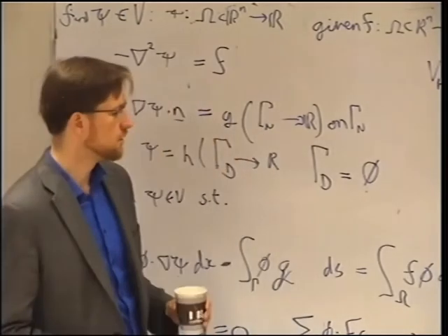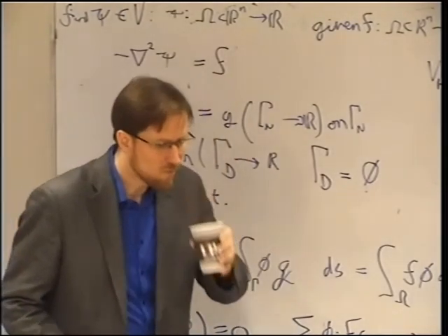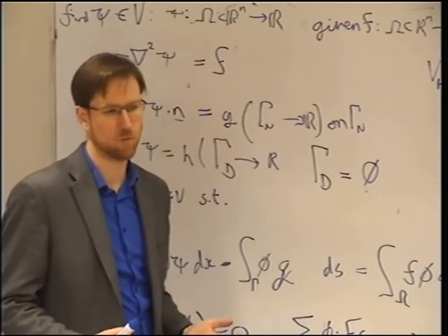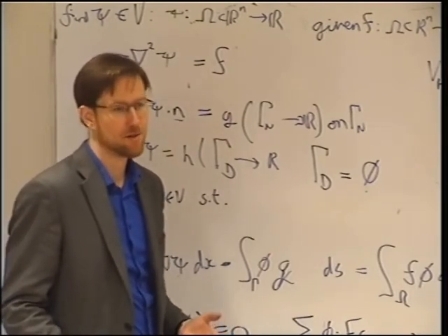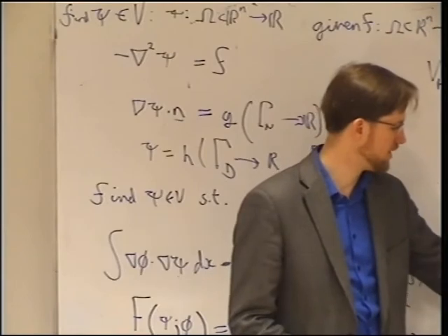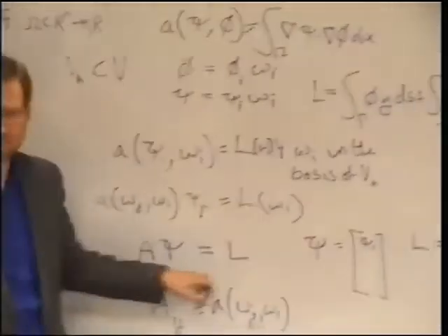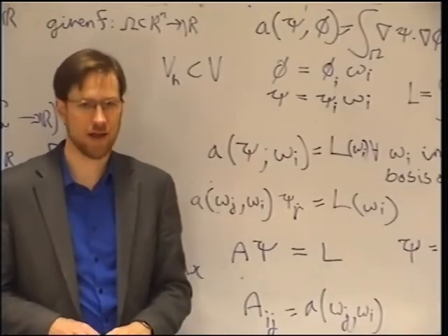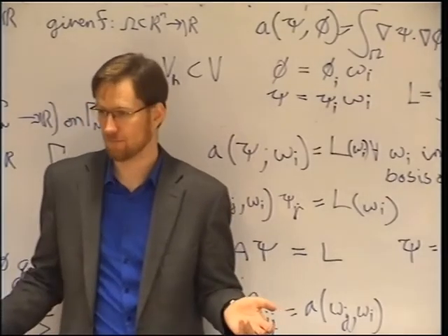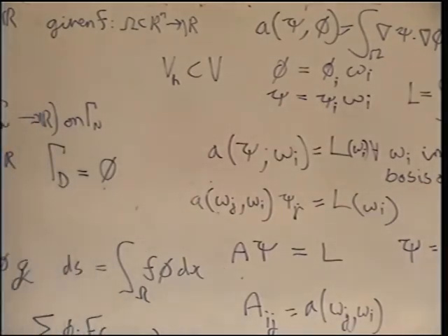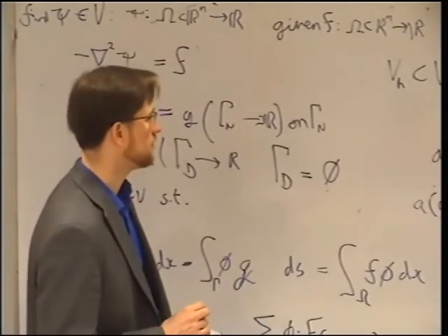And so now there are basically three parts of what actually goes on in a piece of finite element software. There is the part where we visit elements, and on each element we calculate contributions to A and L. There's the part where we take those contributions and put them into the global A and L. And then having built A and L, there's the part where we solve that. And we use standard linear solver packages to do it. So Firedrake always uses PETSc. Fluidity always uses PETSc as well. That's kind of pretty standard.